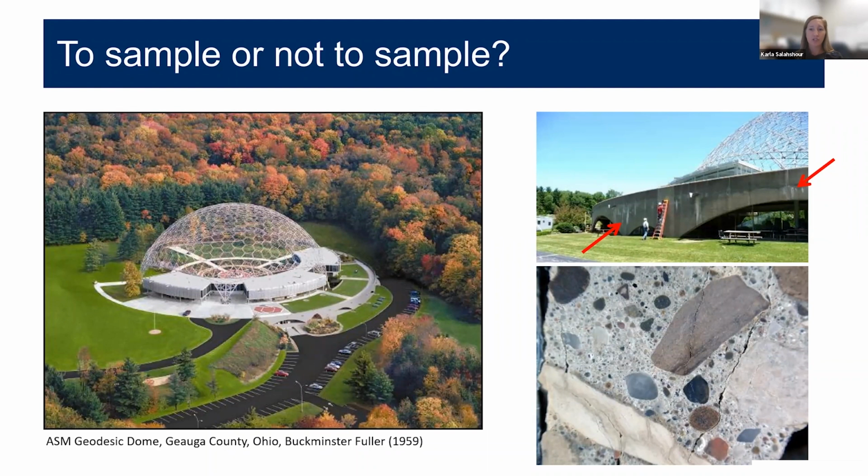And so for this project, trying to determine how and why the structure was leaking could perhaps be solved just with field studies, and sampling wouldn't necessarily be included. However, if we started talking about repairs to the concrete structure, and if those were warranted, maybe that's when we start thinking about if concrete samples should be taken specifically to assess the condition of that concrete.